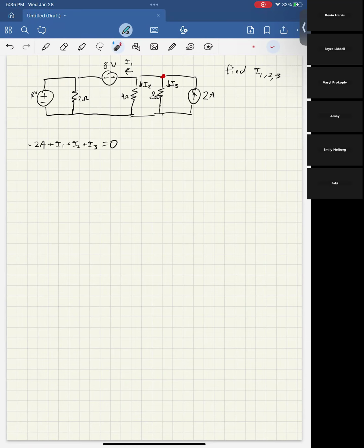So in this case, we've done a KCL, so probably a KVL would be good to do next. So let's pick a loop that deals with 2 of the currents. So for example, how about if we go like this, right? We know the voltage here, we know the voltage here, and we can get the current there, right? This is actually a pretty good loop, because if you were just solving this as you go instead of doing a matrix method, you can just directly figure out I2 here. But I'll go through the loop.